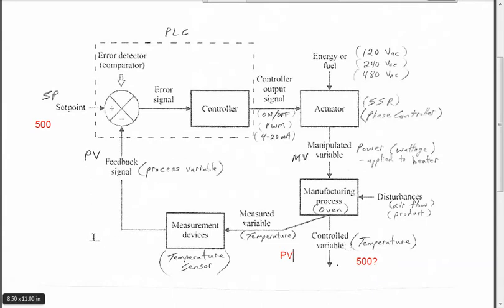And of course, all those things can impact the accuracy of your numbers. Your actual temperature sensor, how accurate is it? And then if it goes to a transmitter, how well is that calibrated? How well is that calibration maintained? Your feedback signal could be coming back in the form of a 4 to 20 milliamp signal, for example.